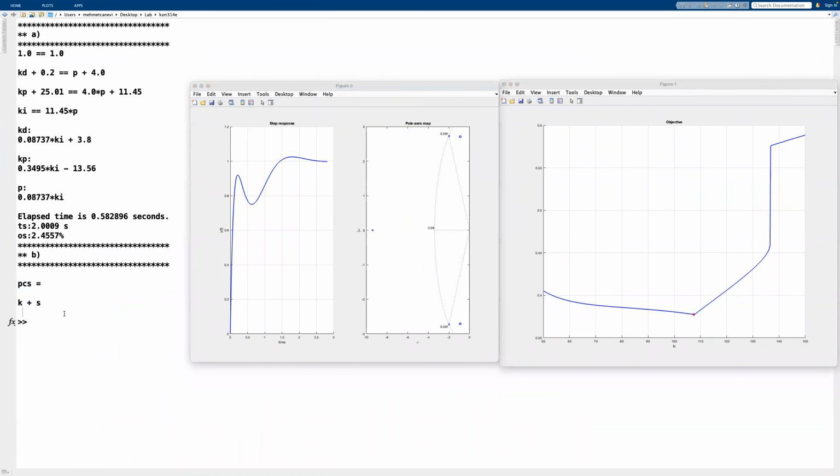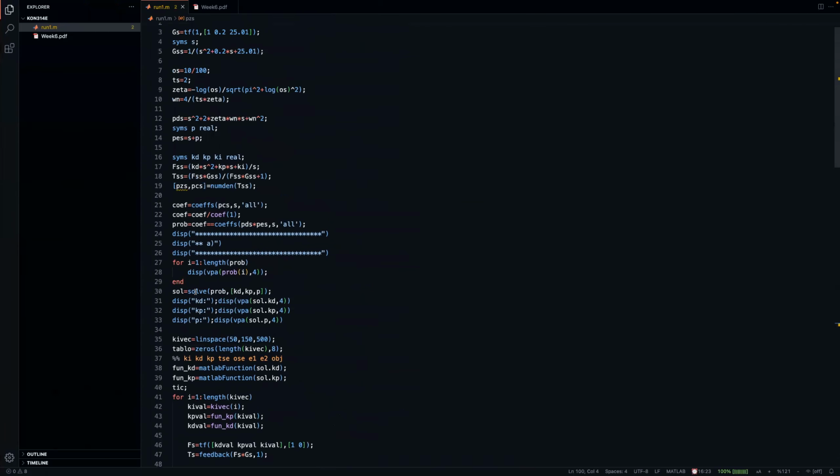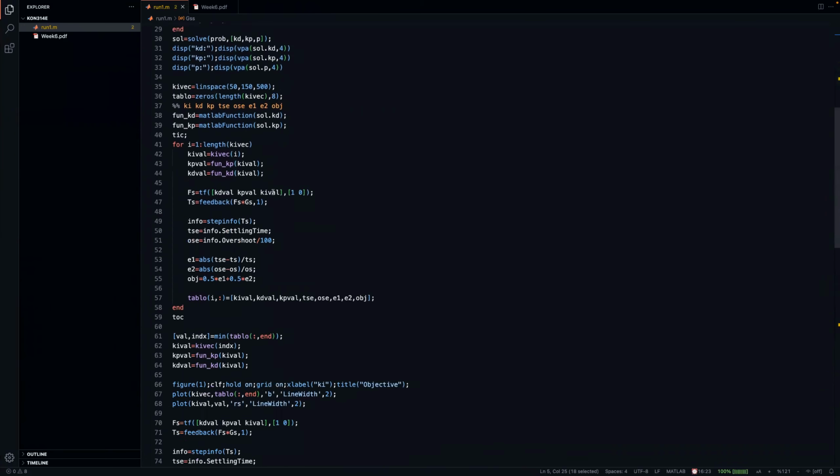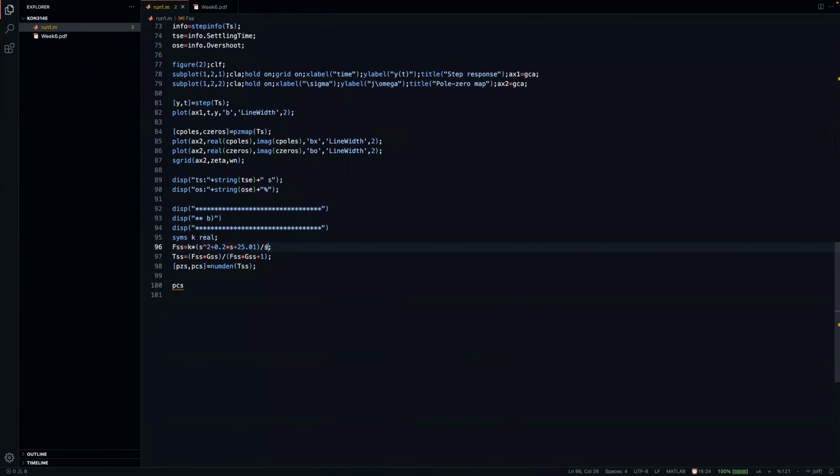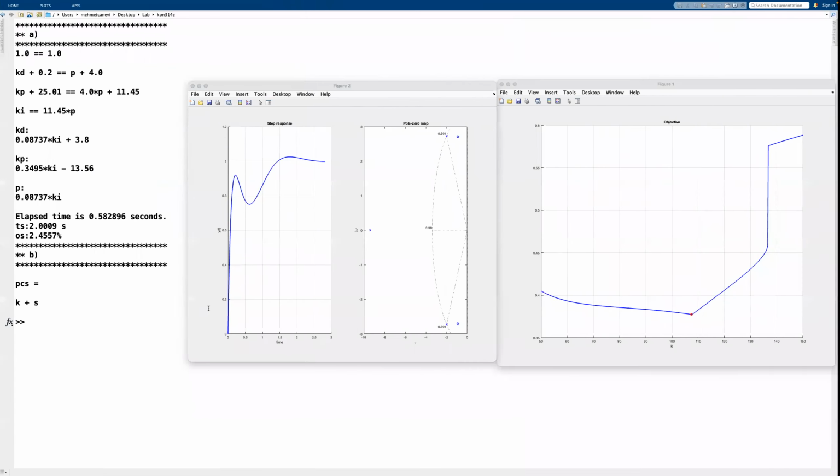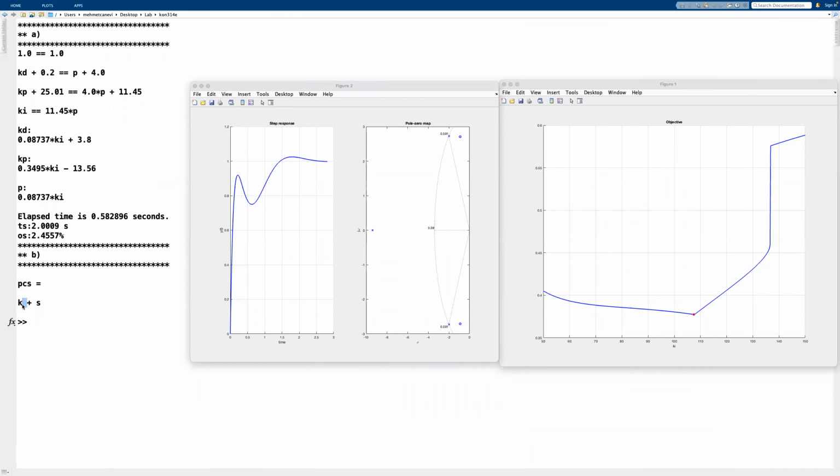Namely, the closed loop is going to be K over K plus s. Now, we did cancel the poles of the system with the zeros of the controller, and we added an additional pole at the origin because the PID controller structure says so. And then we have this gain, which is the only thing that we didn't decide on. And this gain relates directly to the location of the pole. And yeah, it's a first order closed loop because 2 poles and 2 zeros cancel each other out. You can see we place these zeros on top of this pole pair, which means that they will cancel each other out. And the only thing that is left is going to be this pole, which will be decided with the gain K.